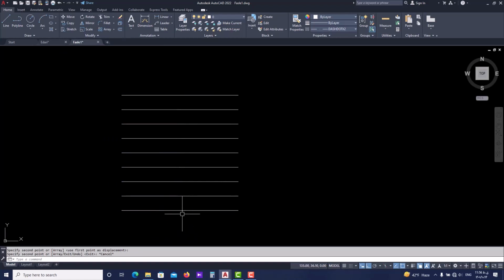Now we need to put a gap between these two sets of stairs because of the fire department rules that we have. We should have a 5 cm to 10 cm gap between two sets of stairs so that the stairs structures won't be attached to each other.